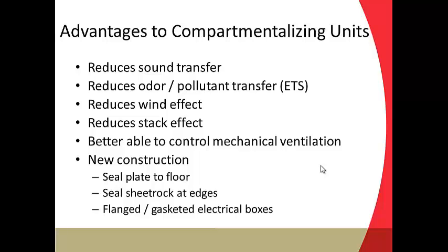Especially with buildings that are framed with metal studs, where all the studs have knockouts to get cabling through or plumbing through. If it leaks in one place, it leaks everywhere. If you try doing blower door guided air sealing, everything you check leaks, whether it's trim on an interior door or a light switch or electrical outlet or cable outlet on an interior wall. Everything is going to leak. So doing that airtight drywall approach goes a long ways towards making that building much more compartmentalized.